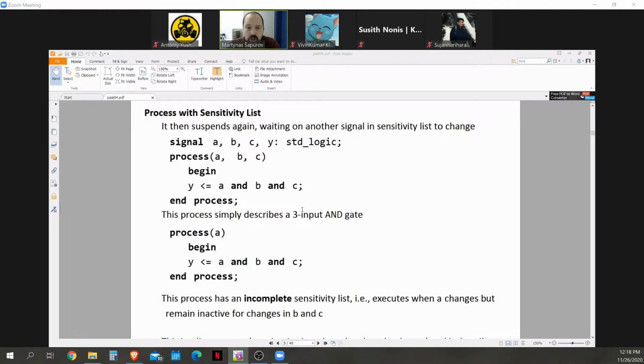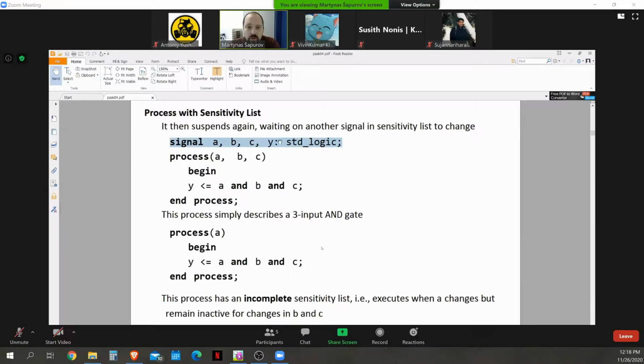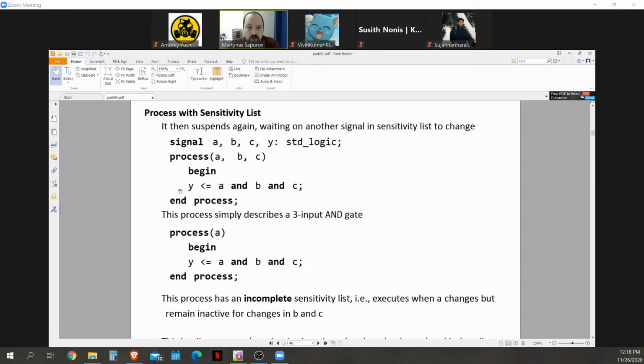You have to add these 2 processes into your program with a certain entity, which has the signal not in the signal part but in the entity side, and you should probably have 2 outputs, y1, and here y2, and then build a test bench program, and you'll have to show me how this result differs from this result at different circumstances.